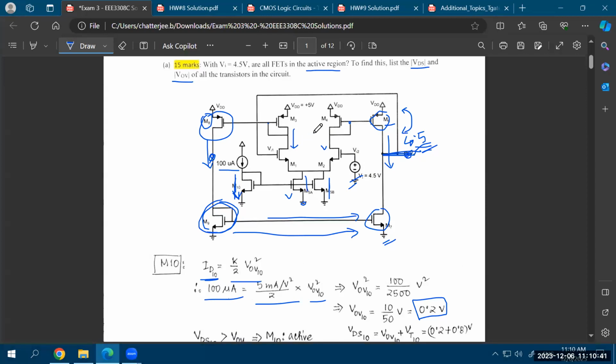These 2 branches? These 2 branches. So that's the property of the differential amplifier, right? Remember that if you have this single current source at the tail, and you have 2 input transistors, and you have 2 load resistors, that was the basic structure of the differential amplifier that we studied in the beginning, right? So in the scenario when the DC potentials of these 2 transistors are the same at the gate, let's say this is VG1, this is VG2, those are the 2 gate voltages.